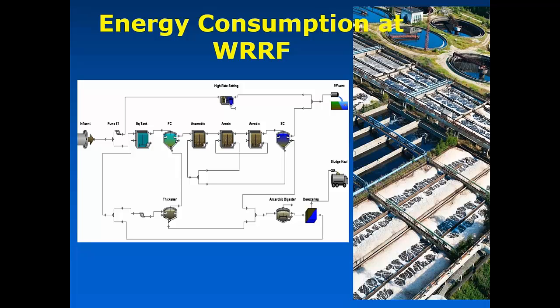So as I was saying, energy consumption is a key element of operating any wastewater treatment plant, and as you probably know, aeration, as we can see here, the amount of air that's required to do the mixing and drive all these bubbles that we see in the overhead view of these aeration basins here is quite significant. It can make up to about 50% of the total energy cost to run a wastewater treatment plant. But second to that is usually the pumping of the liquid itself.